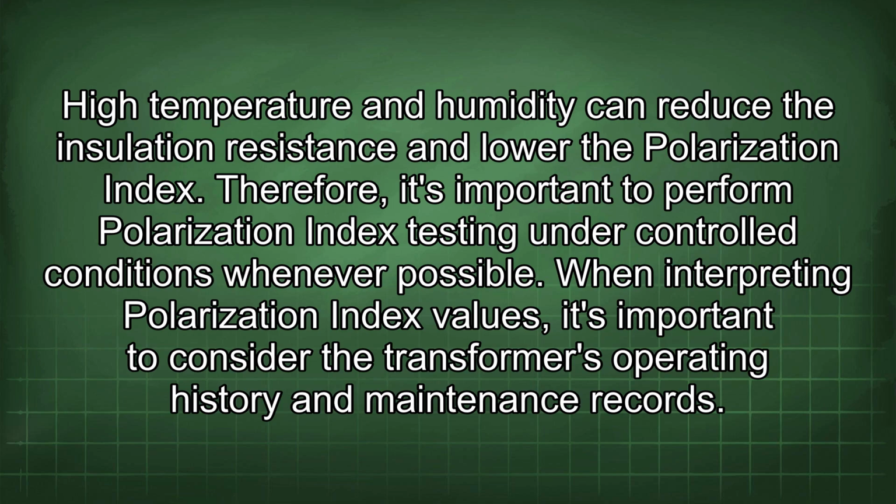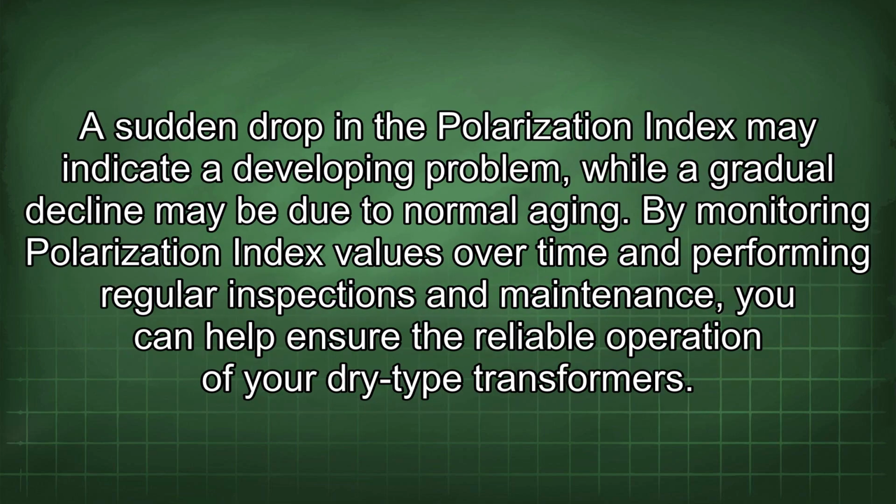When interpreting polarization index values, it's important to consider the transformer's operating history and maintenance records. A sudden drop in the polarization index may indicate a developing problem, while gradual decline may be due to normal aging. By monitoring polarization index values over time and performing regular inspections and maintenance, you can help ensure the reliable operation of your dry-type transformers.